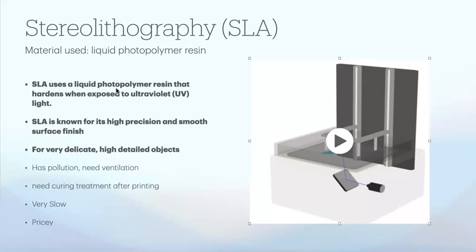So SLA is good for making high precision and smooth surface finish objects, and you can make very delicate, high detail objects. But the problem is that it has pollution and you usually need ventilation because it can cause allergic damage to the human body.